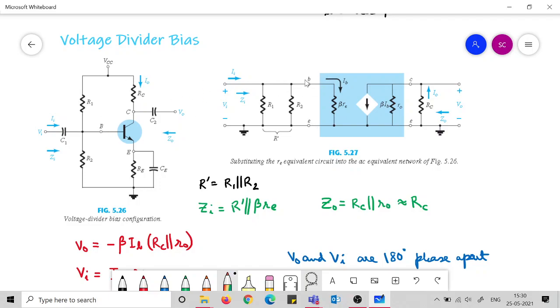So after that you have this current that is flowing. So here there would be an IB setup and it would flow through this diode junction which is giving it a resistance of RE, and if you reflect this resistance to the input side in order to make it a wholesome resistance, it would be beta RE. So beta RE resistance is there.